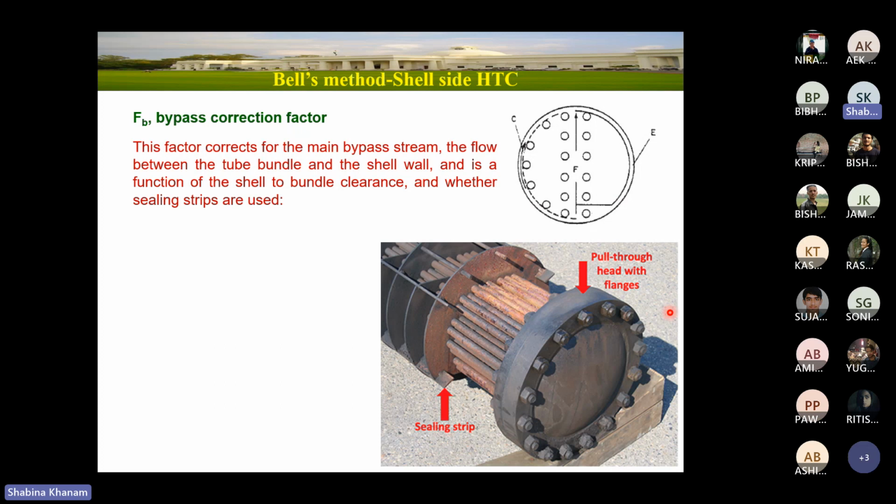If internal floating head is there, you need to put the sealing strips. Without sealing strips also it will work, but that condition you need to check.